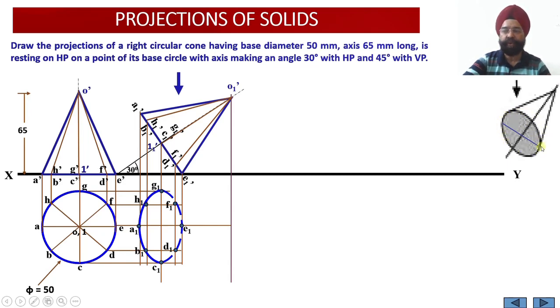So this semicircular portion will be hidden by this particular surface because of the incline, which is quite apparent from here. This is visible, whereas this portion is not visible. So this is an opaque solid. Since this is an opaque solid, projections corresponding to all the points lying on the interior side will be drawn dotted over here. So this is the significance.